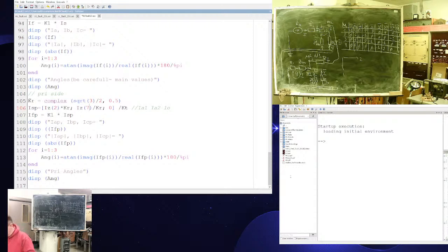If negative sequence current flows through such a transformer, it will be subject to rotation clockwise by 30 degrees. Here I have the rotation factor, a cosine and sine of 30 degrees. By multiplying with this factor, I will rotate the current in the second branch, which is my transformer in the direct sequence schematic, forward by 30 degrees.